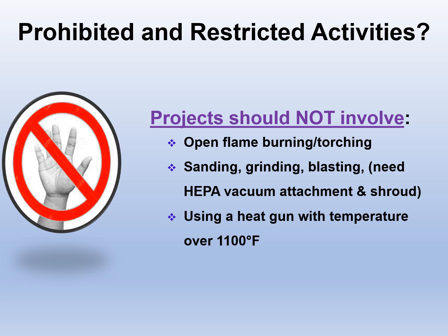Also, you do not want to use a heat gun with a temperature over 1100 degrees Fahrenheit. Using a heat gun over this temperature could greatly increase the risk or danger of fire, and a fume could be created where a gas or vapor could be dangerous to inhale.